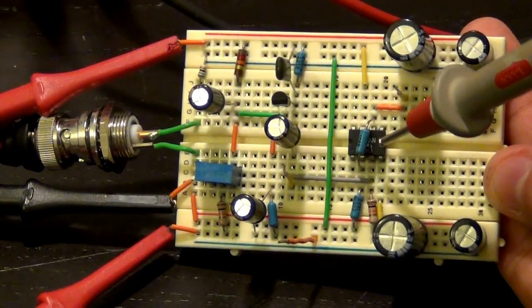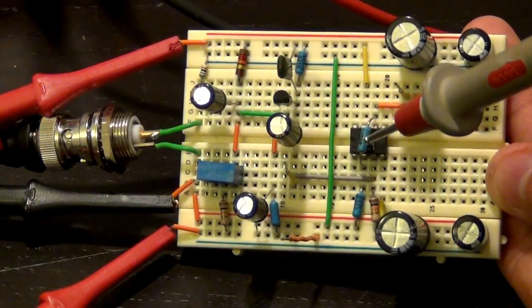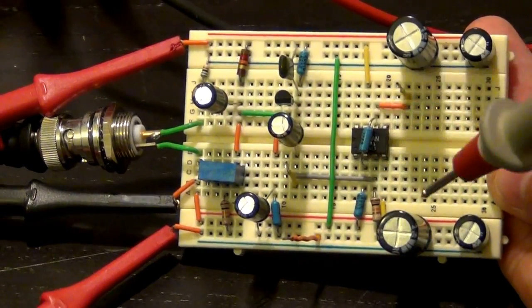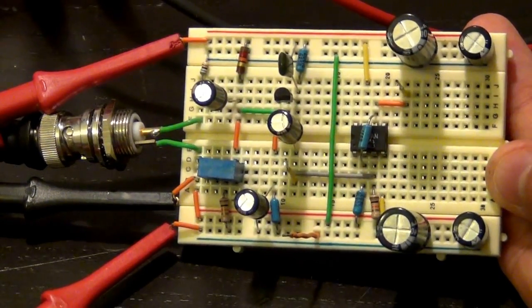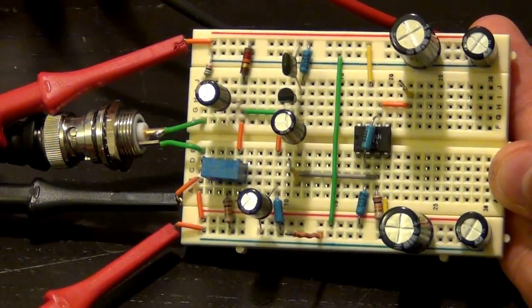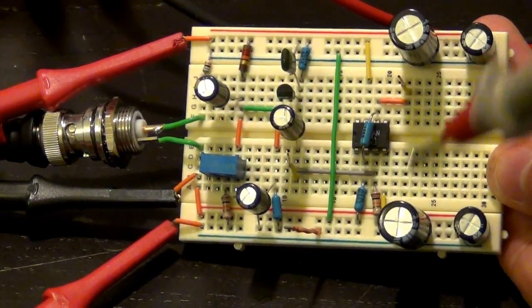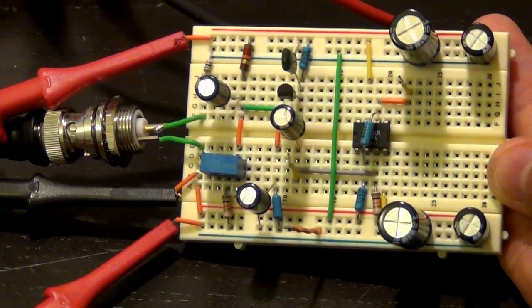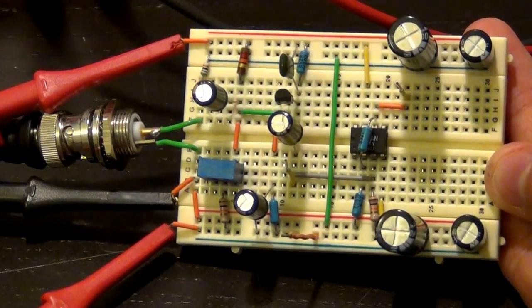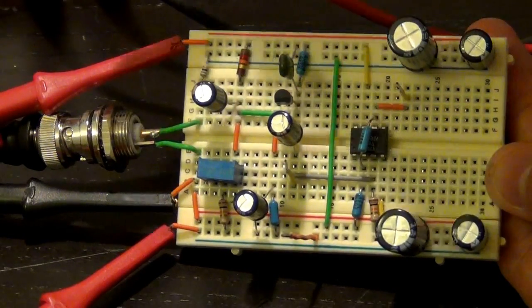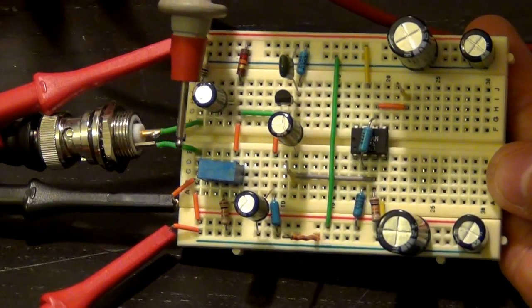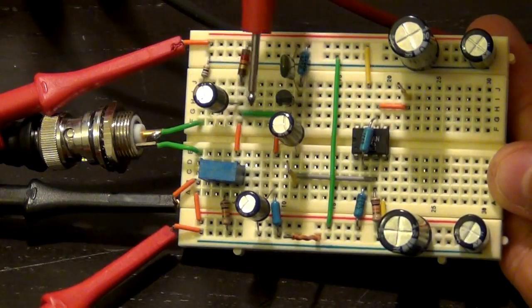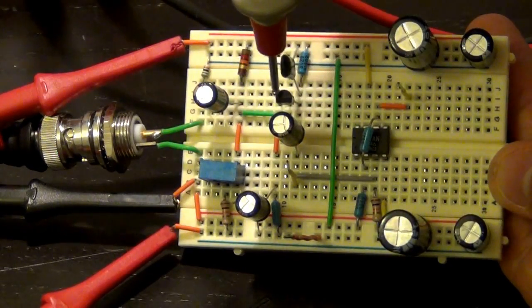And here's our second stage amplifier, which is just an op-amp in feedback with 2 equal resistors, and this is an offset cancellation resistor that I have added, which is not in the schematic. And I have 4 large decoupling capacitors to reduce the noise on the breadboard. So the input signal is going to come from here, go through the series capacitor, and be applied to the bipolar transistor.